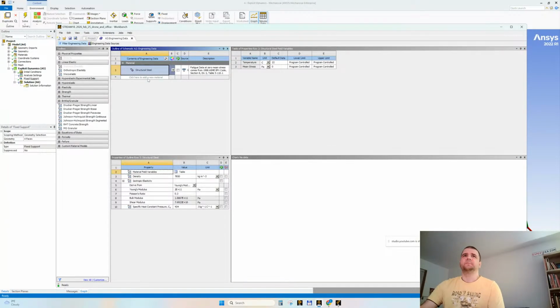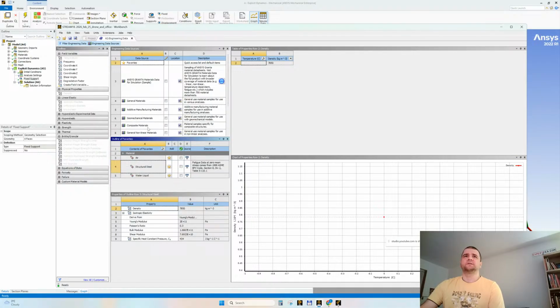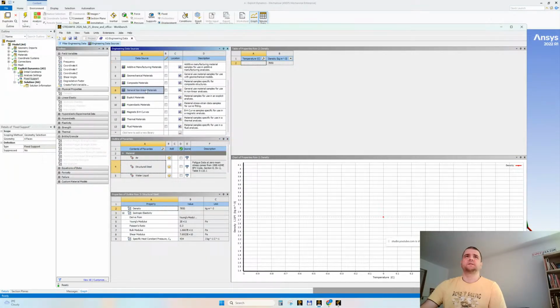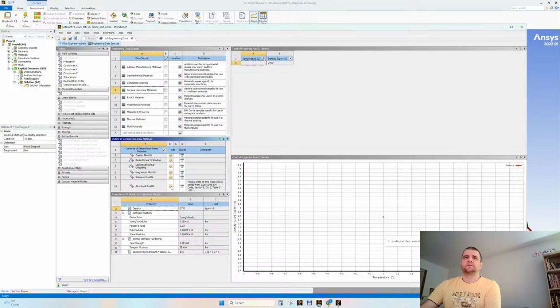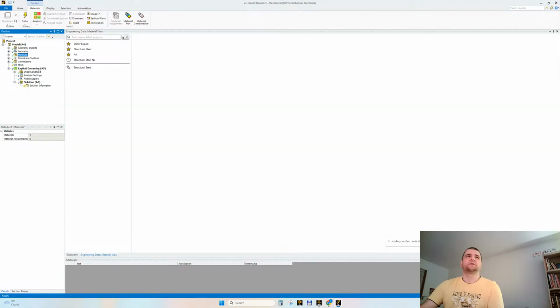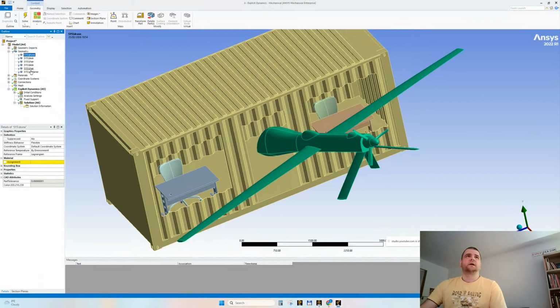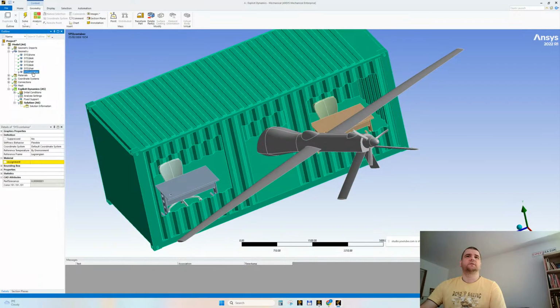So let me delete the default steel. And I always advise to go with nonlinear materials, either from this library or from the explicit dynamics library. Structure steel. All right, right-click here, refresh materials. Now, let's assign everything to be of aluminum, and this structure steel, non-linearly defined.